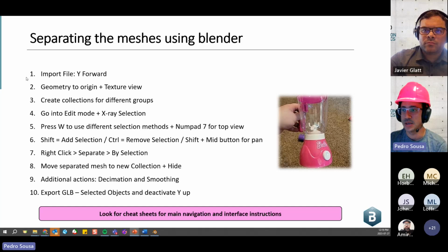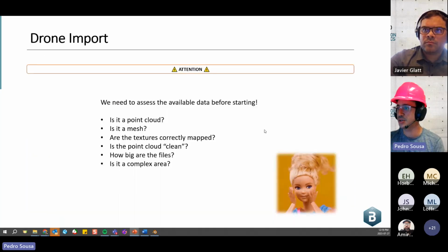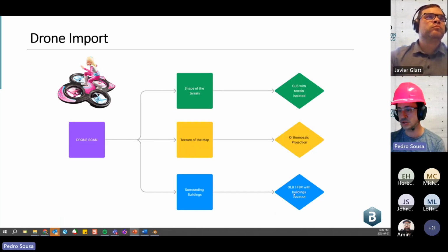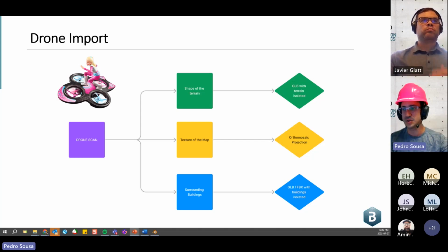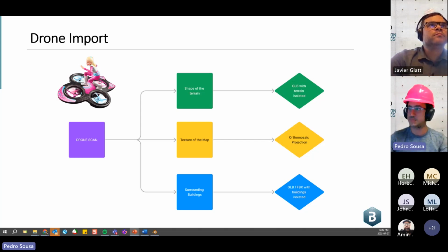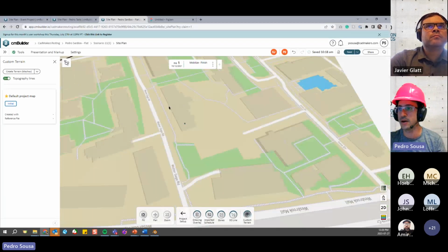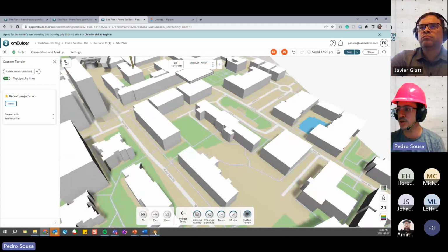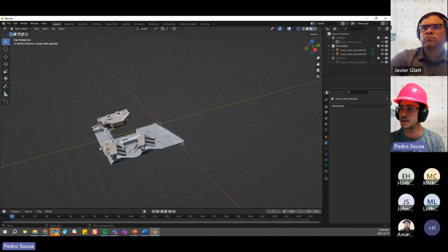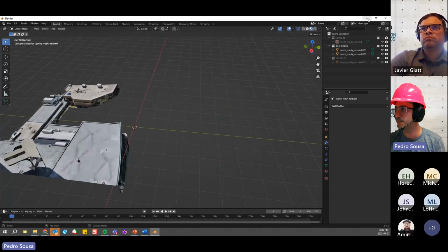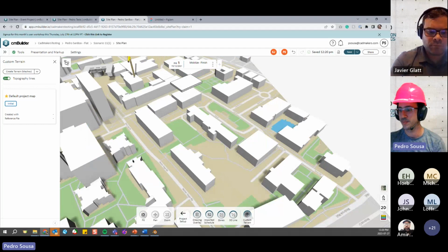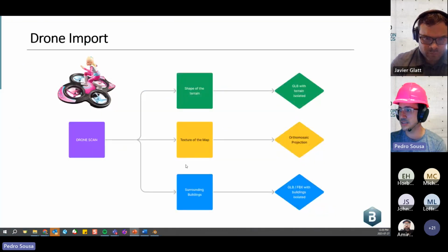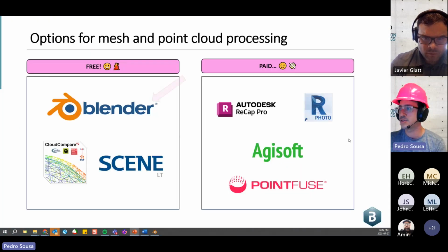Awesome. Exactly. So this process is just to get to the point where we have a shape of the terrain isolated and everything else also isolated. And then you can import those things to have them as your references for surroundings, better than the white shapes that are generated automatically over here in Builder. So if you want better shapes than this, you can simply isolate your buildings and then bring them over in cmBuilder and position them correctly. Okay. Cool. Awesome.